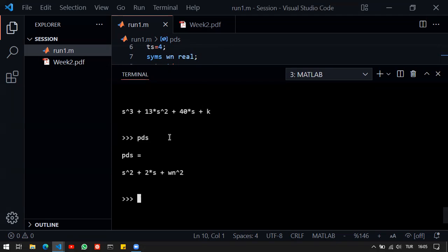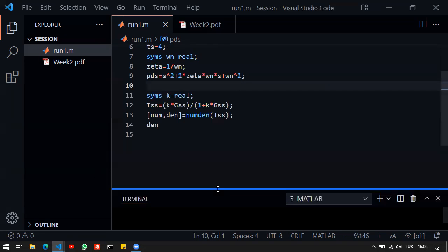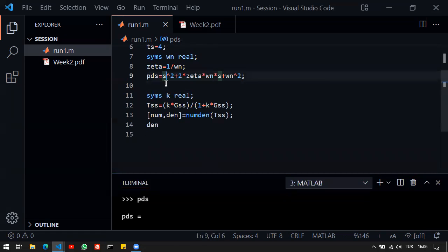So in order to be able to choose certain controller, I have to add another pole in order to match the degrees of the polynomials. And then I'll take all the coefficients of the terms and I will equate them to each other. And if I solve that, I'll get my controller. Also the details of my solution, if it's possible. So basically, the step here is to define another pole, because it's a third order one and I only decide on 2 of them.